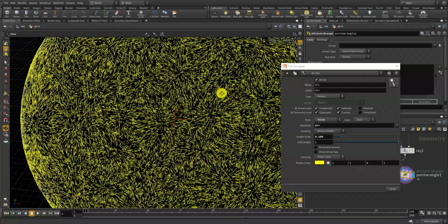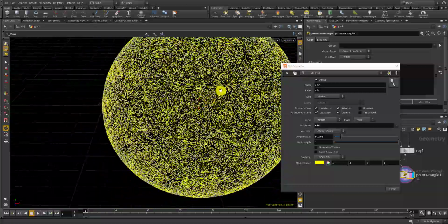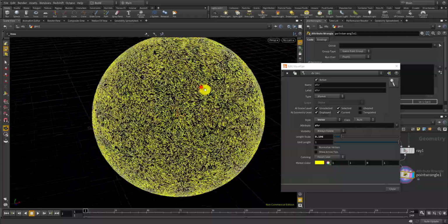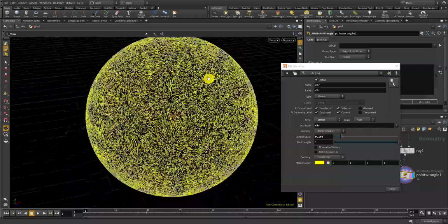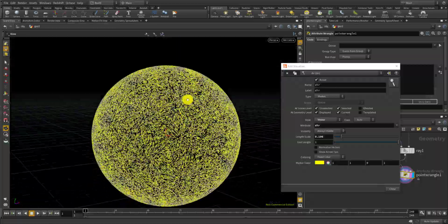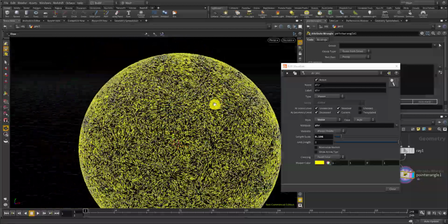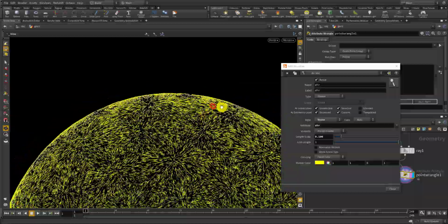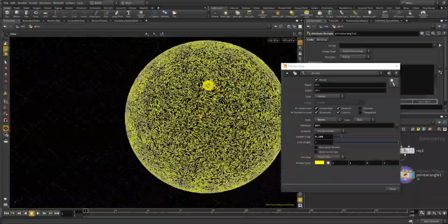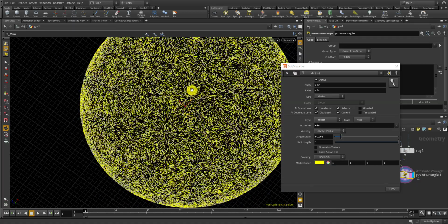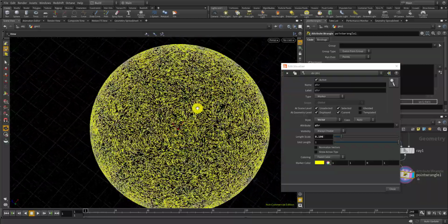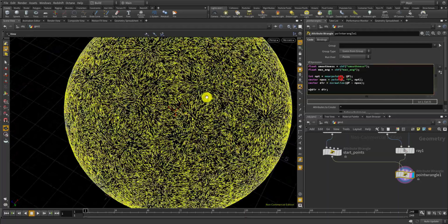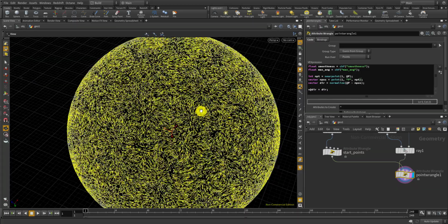Each point has its direction from the starting points outward, like 360 degrees. And if you look from far away, it does make a Voronoi cell looking pattern like this. But right now, as you can see, the vectors are too straight, and if you use this for the frost generation, the frost will become pretty much straight as well, which will look pretty artificial. So let's make a noise function to randomize this flow vector field a bit.